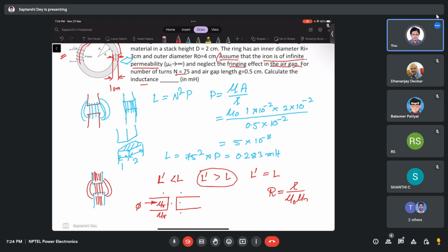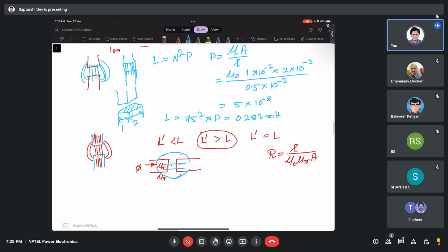Basically, if I now draw some lines here, with blue, say this is one line, this is one line, this is another line. All these lines are possible paths that the flux can take. Possible parallel paths, out of which the least reluctance paths see the most flux flowing through them, and the highest reluctance paths see the least flux flowing through them, just like in an electrical circuit.